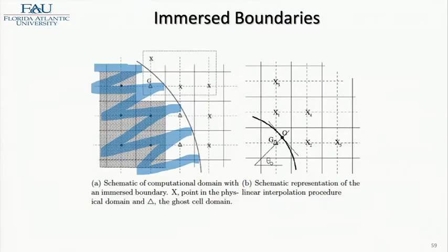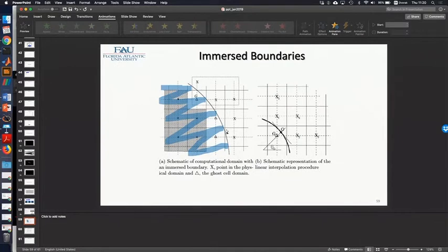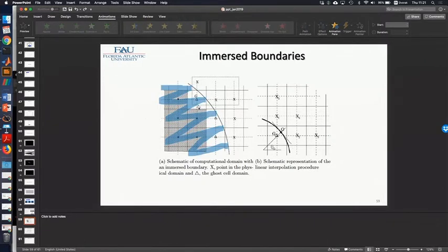So if we look at immersed boundaries, for instance, let's stick with a circle or a cylinder. So this is the inside of the cylinder, right? And I have my surface of the cylinder. Everything outside is in pure fluid. So first of all, you designate these points called ghost points, where you know the velocity. It's the velocity of the solid.